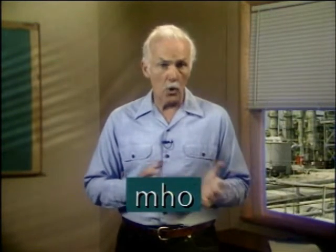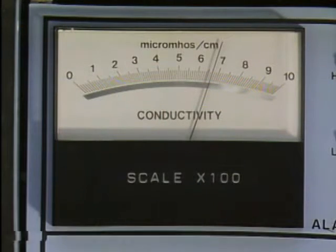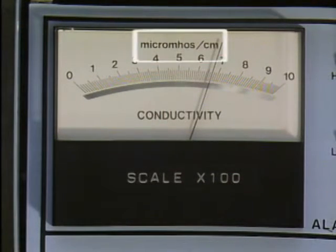Now, the way a conductivity measurement is expressed can depend on the units of measurement that are used. For example, ion concentration is sometimes expressed directly, either as a parts per million measurement or as a percent value. But electrical conductivity can also be expressed using a basic unit called the mho. A mho, which is ohm spelled backwards, is the reciprocal of an ohm. While an ohm is used to describe a substance's resistance to current flow, a mho is used to describe a substance's ability to conduct current. Many conductivity analyzers use units of micromhos. A micromho is 1/1,000,000th of a mho.